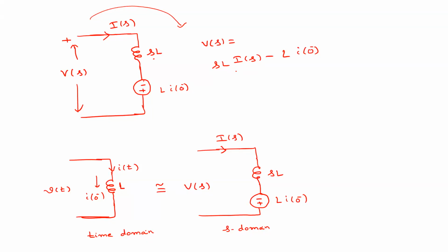Okay. So this is the time domain approach, and this is how we are converting into S domain to apply the Laplace, right? This is the voltage source based approach. Similarly, in this equation, what is I of s? What you will get if you apply I of s? Just divide this one with sL, right?